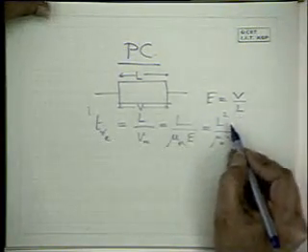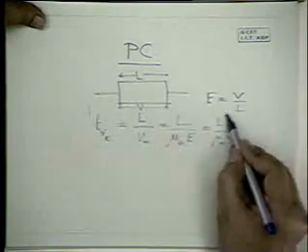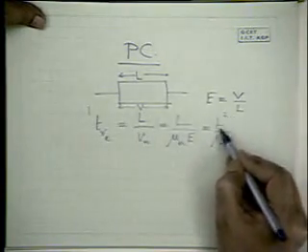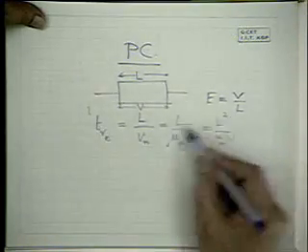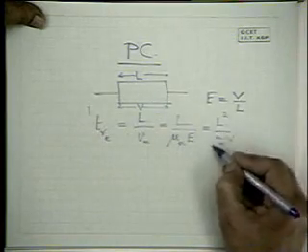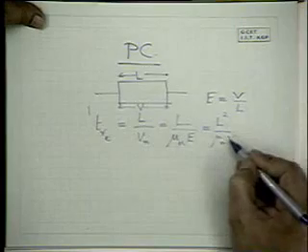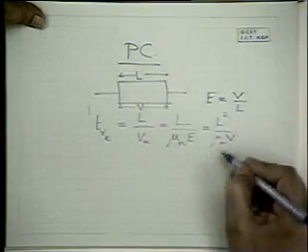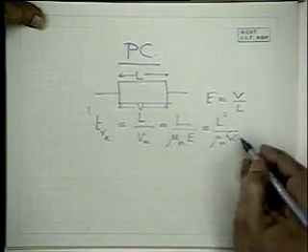We can see that the transit time is directly proportional to the length of the sample squared. So if you can reduce L, the speed will improve. An important material property is mu. If you have a material with high mobility, then the speed will be high. And of course, the applied voltage V is something that we can vary.